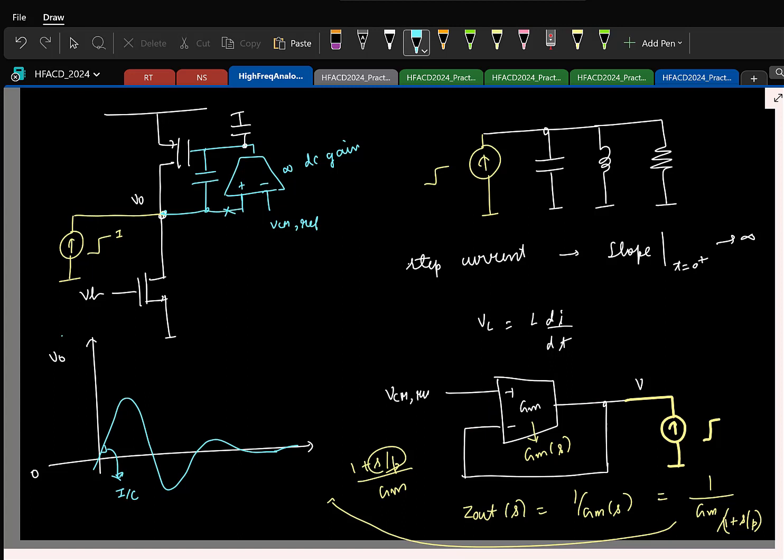So in the previous case, when we took the capacitor as 0, we took the inductor here. Correct. But that output node will be attached to CL. In addition to the CL, you will have inductance, right? The capacitance here is coming because you will have a load capacitor or some parasitic capacitor here. But that will be very high, so how can we simplify this? That is okay. What I'm saying is, if you were to model the total impedance, you know that the capacitor is going to come. That is included. In addition to that, what all we have? So you first ignore the capacitor and see what is the rest.